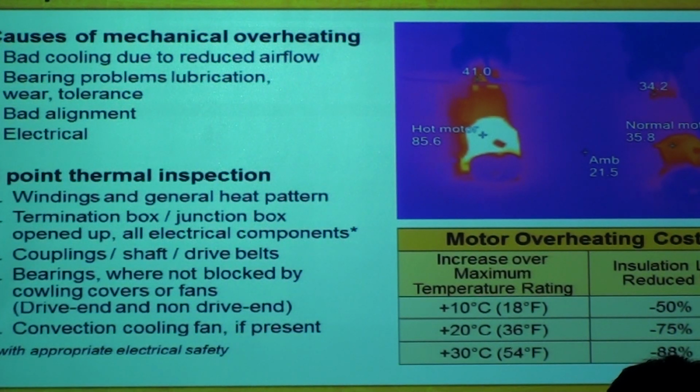If you're measuring 10 degrees more than that, guaranteed you've lost 50%. Because if the surface of the motor is reading 80 degrees, and mind you, you are reading the surface, okay? Between the surface and the winding, there's a lot of gap there. What you're reading 90 degrees here might be 120, 130 degrees on the winding. So it's typically 20 degrees cooler than the winding temperature.